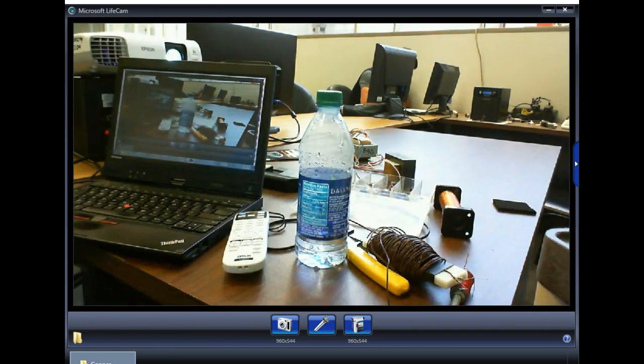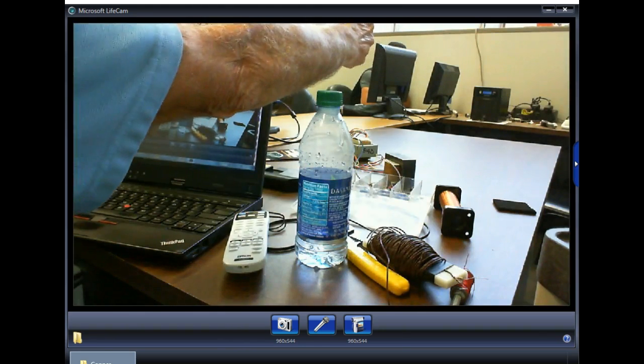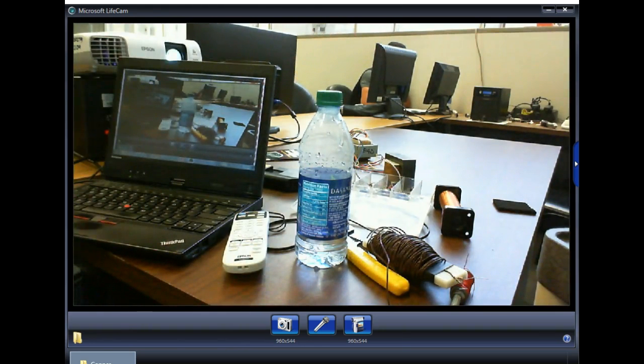So I don't know if I put the NEMA things up there or not, but I'll do that. That shows you all the receptacles and all of the plugs and everything, what their currents are rated for, and all different types of things too. So 240 would have a different plug like that. Even though I could legally wire that plug over there for 240, it would never pass code, right? You understand, because it's a different plug. So you've got to use certain plugs for certain receptacles. So here's the Romex.